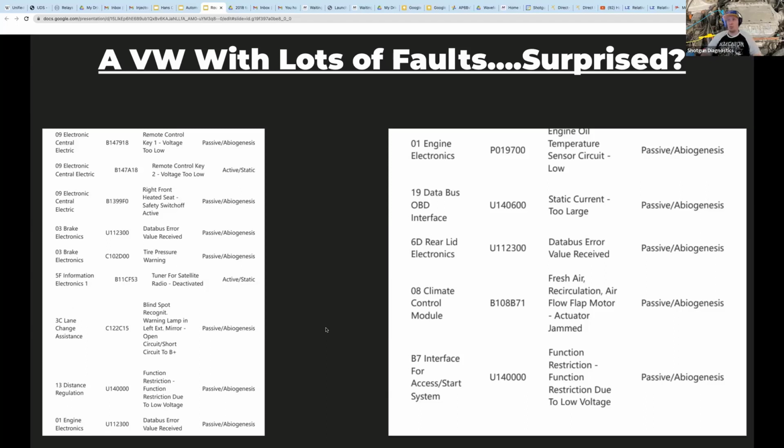Now, each of those power supply style chargers has different capabilities, right? Some of them you can modulate and change the set voltage or the voltage set point. So you can say, hey, I want it to hold it at 13 flat or 14 flat or 13.5. You can choose. And some OEMs are more picky about what voltage they like. But suffice it to say that if you're trying to memorize a learned value like an ADAS calibration, you need that voltage to stay steady so the control unit is happy. So a steady power supply will do that. And so you want to make sure you have one of sufficient amperage capabilities.